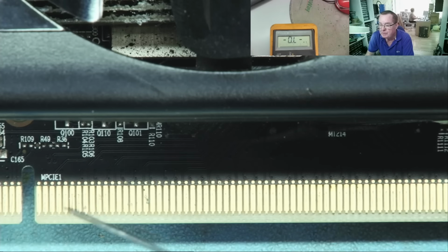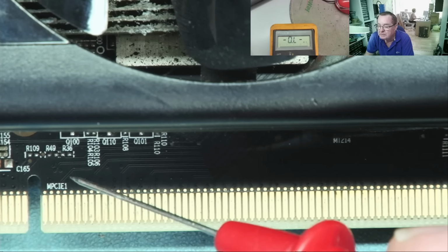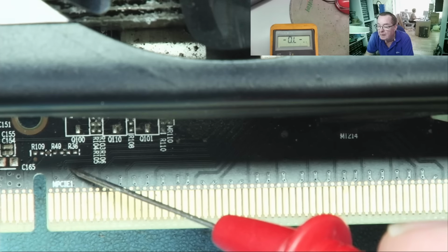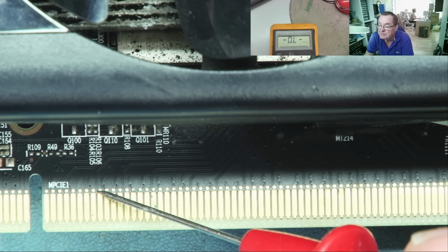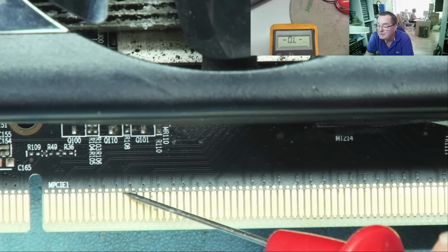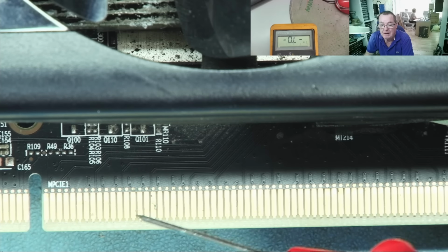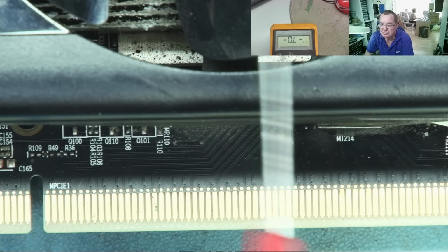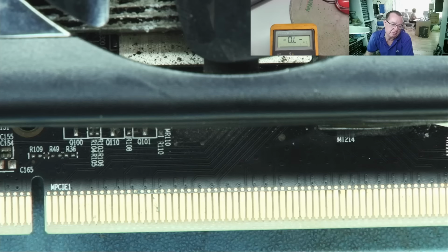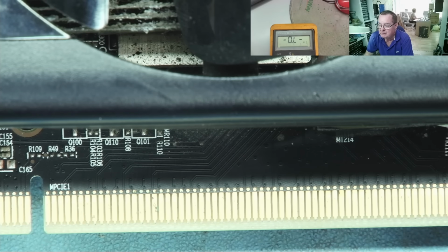So if you look at this one, you can see that there's 2 wires coming down here. Okay, there's 2 more coming to there. Can you see them? 2 more coming to here. The ones in between are grounds, okay, and they're just for shielding between the lanes to stop crosstalk, if you like, because these have very high frequency signals on them.